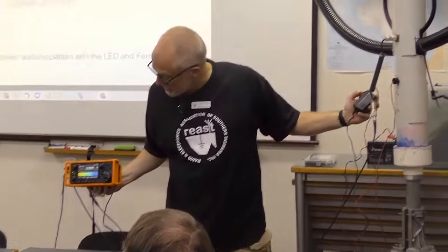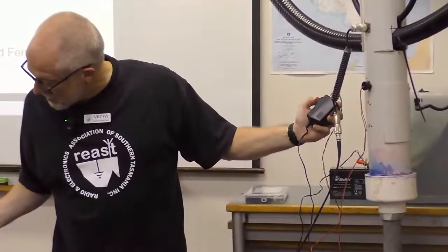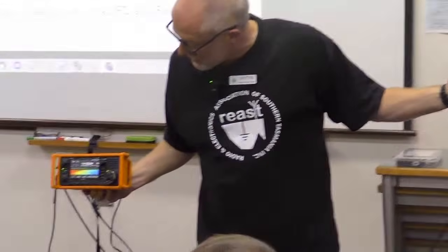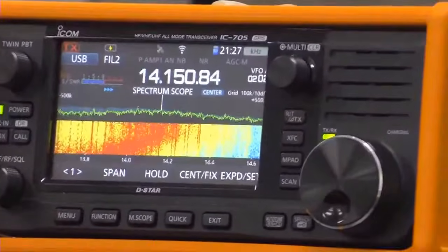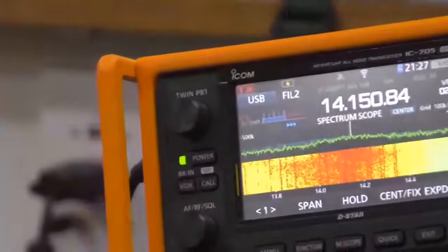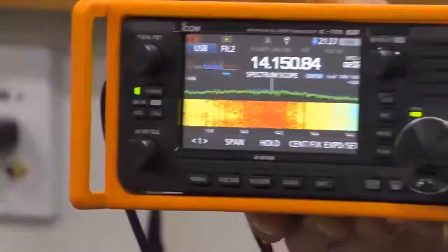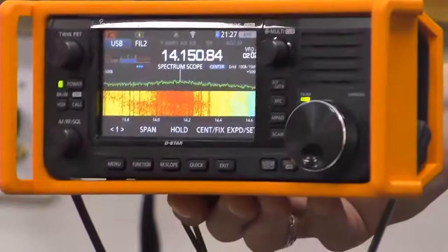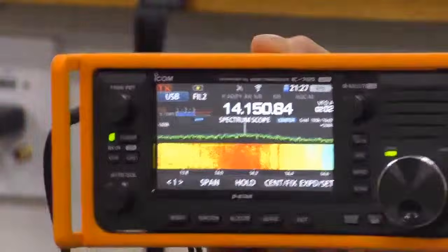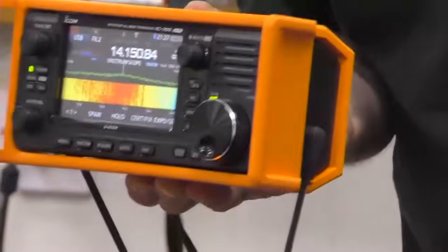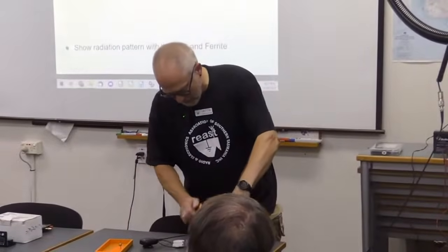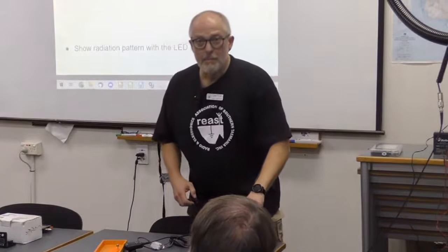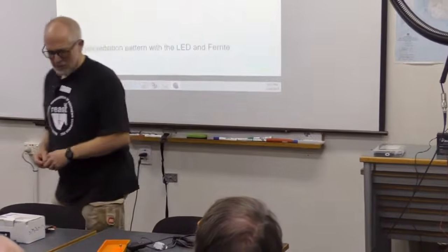Now, the key thing to mention there is when you get it tuned to the right, like about there, where you're in the most noise, you're also in the most signal, but you're not hearing anything either side of that. Well, very little. Sorry, that's not a correct statement. Very little of what's next to it. So I just wanted to demonstrate that's the bandwidth arrangement of the antenna on a waterfall.